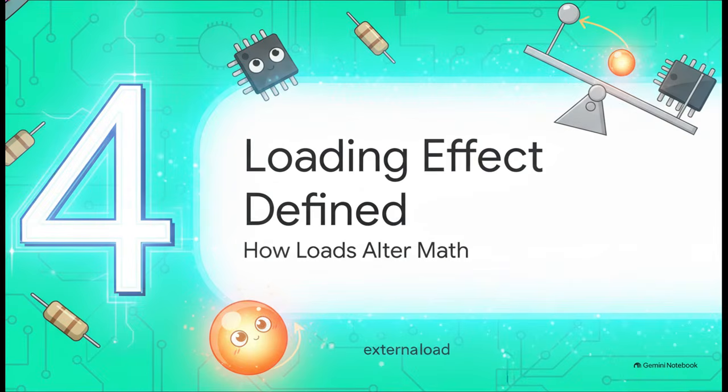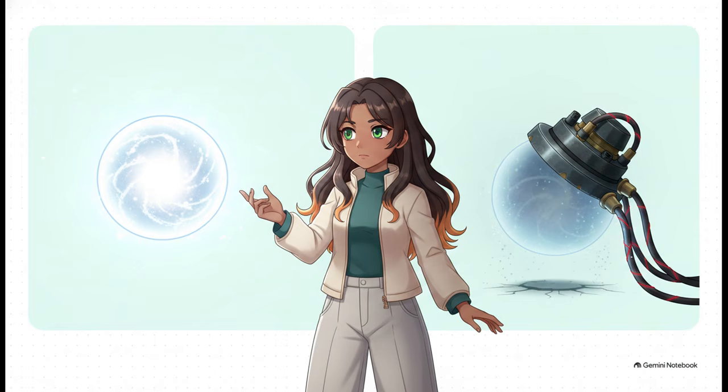So let's get into it in Section 4, Defining the Loading Effect. So what's actually happening under the hood when we attach an external load to our perfectly balanced divider? Well, if you compare the ideal state with the real state, you quickly see that plugging a component in fundamentally changes how the whole circuit operates. Think about it. With no load, you get this pristine open circuit output voltage. But add a load resistor, and suddenly your output voltage diminishes. Why? Because that load is demanding a larger current, which ends up acquiring more total power from the original supply. You're basically bleeding off energy that the divider just wasn't accounting for.